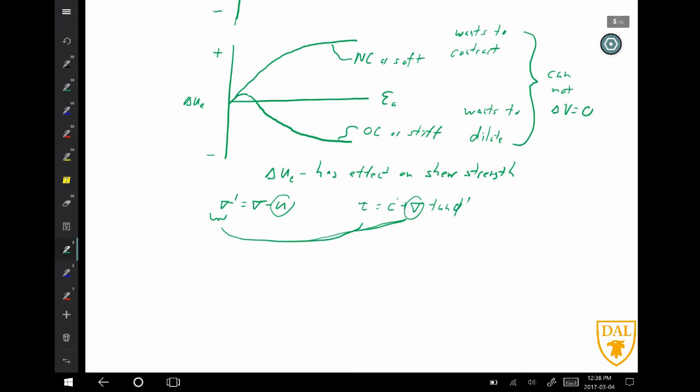So if you look at this plot here of excess pore pressure, basically the pore pressure is changing in a fairly complicated way as it's loading. And it's very sort of difficult to know exactly what is going to happen in a field scenario as shearing induces. So instead, we simply carry out the test and come up with the undrained shear strength, which incorporates directly the changes in pore pressure going on inside of the specimen.